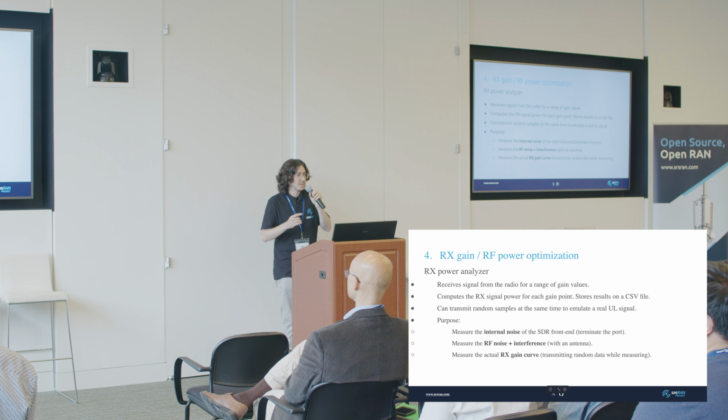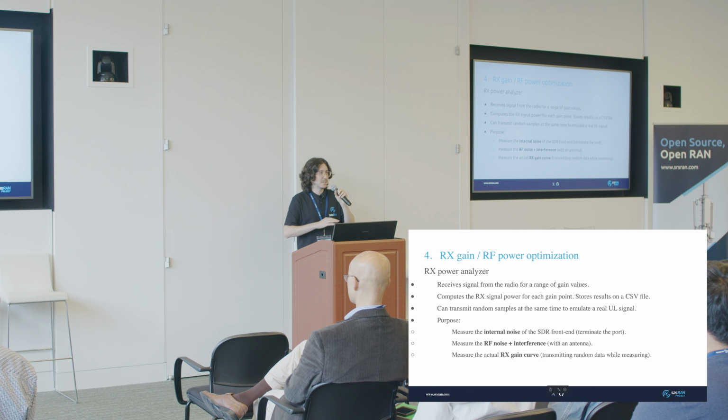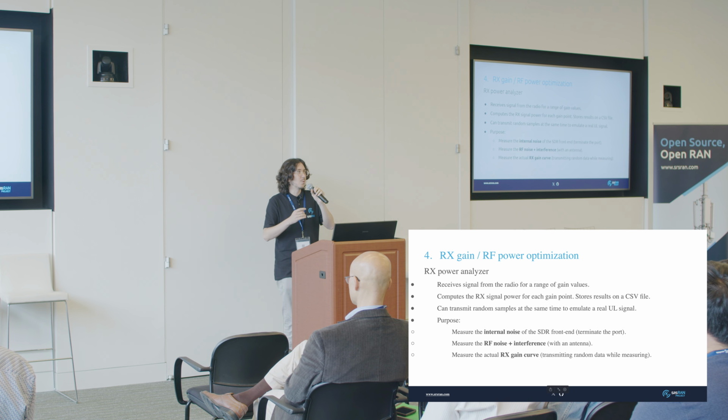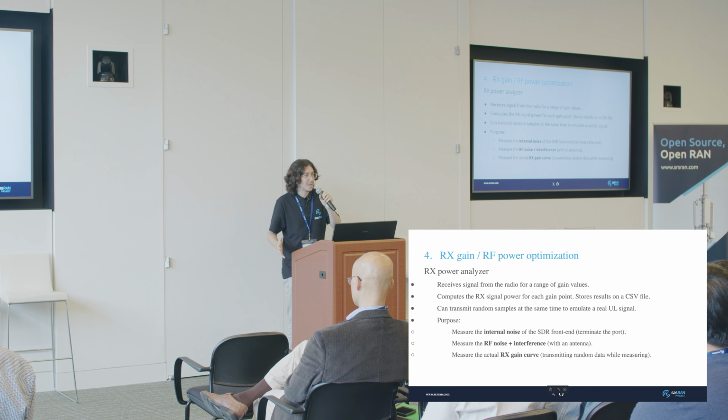In a modern receiver, you have many places where some internal resistors change that control the total receive gain. So when you move above a specific value, you will see, oh, now this resistor changed, and maybe if I increase the gain by 1 dB, it doesn't result in a 1 dB increase. Maybe it's half a dB, maybe it's 2 dB. It depends on the transceiver.